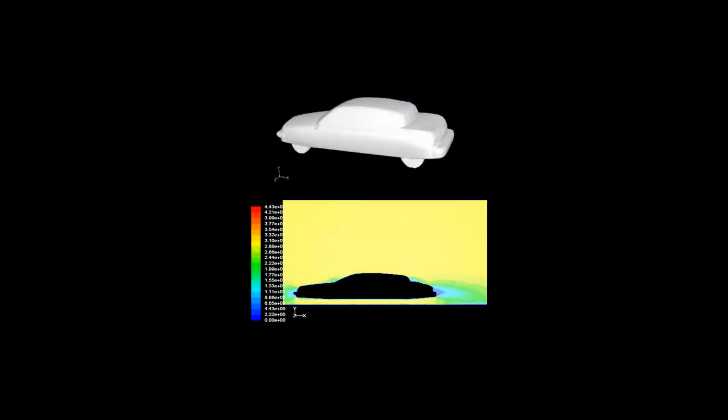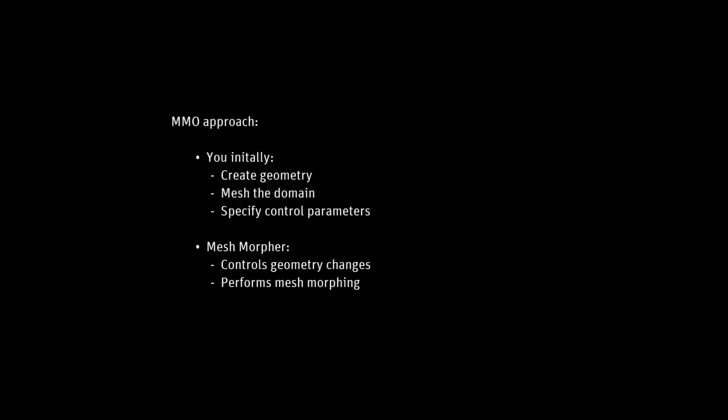When using the Mesh Morpher, you need to create geometry, generate mesh, and specify a matrix of control points only once, and the Mesh Morpher will automatically apply geometry and mesh changes in the solver.